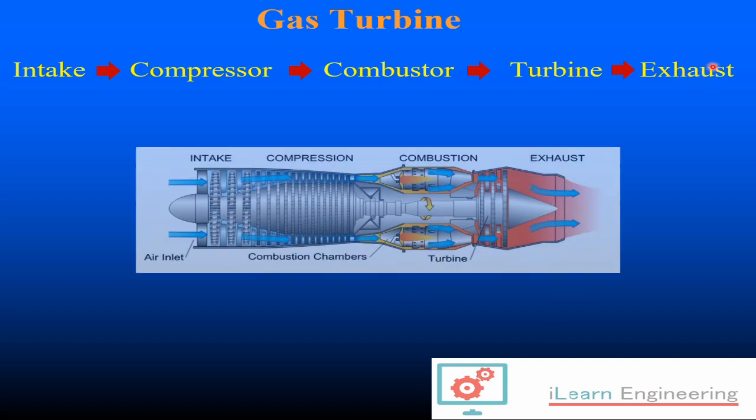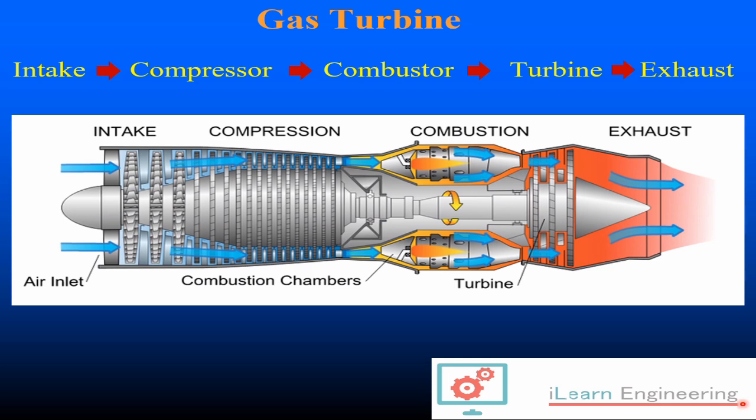And a typical cutaway section of a gas turbine is given here. So here you can see the air inlet. We go through a compressor, which increases the pressure, into a combustion chamber, through to a turbine, and that turbine is connected through a central shaft to power the compressor. The gas exits the turbine through a convergent nozzle here, where it then exits to atmospheric pressure, and we have a thrust producing machine.